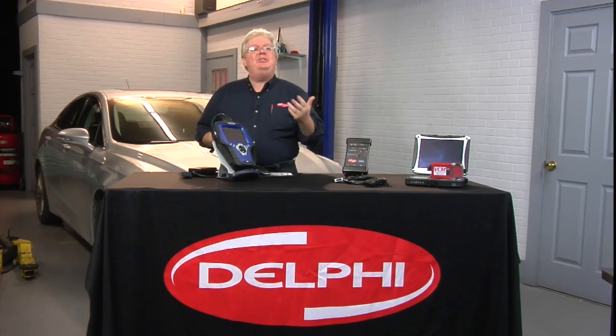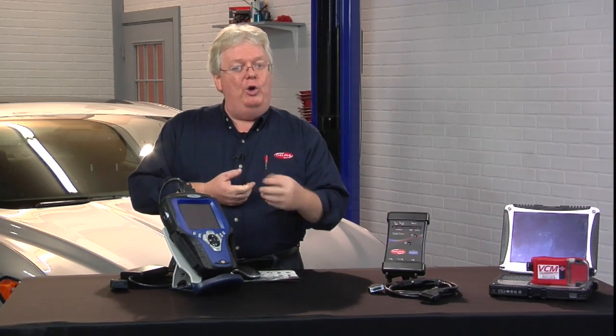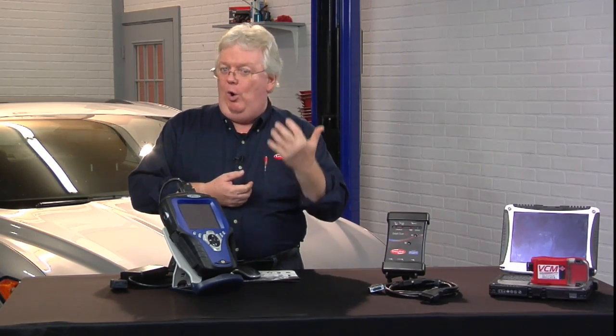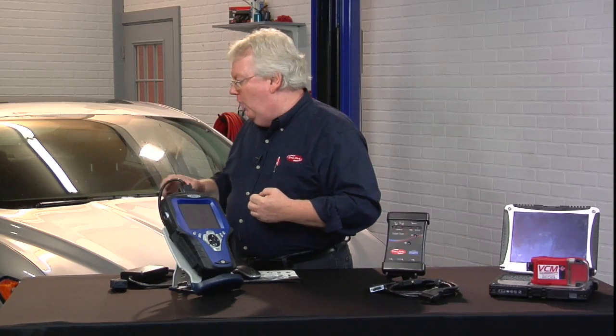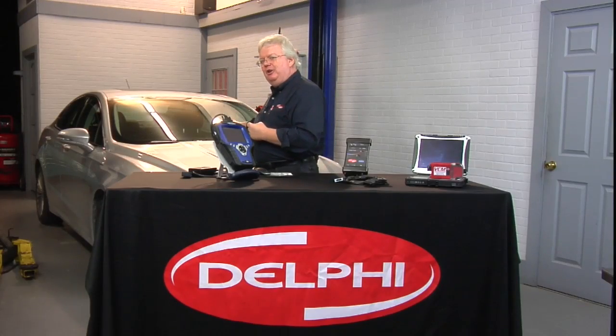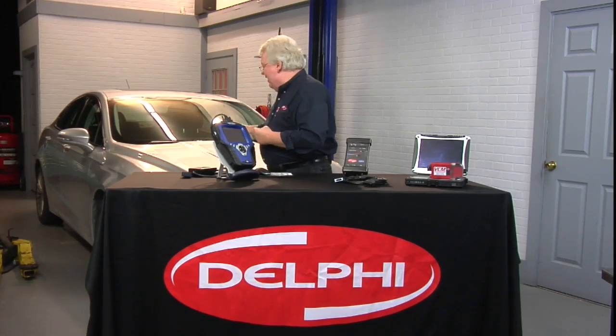Now, comprehensive components, whether it be engine controls or transmission controls, consist of solenoid outputs, sensors, things like that. Those monitors always run. They'll always say complete because we're always checking to see if that mass airflow is putting out a signal or if that throttle position sensor is not below half a volt or, let's say, above 4.5 volts. It's somewhere in that working range. If it falls out of that range, it's an open or a short, we should set a code because the monitor for that runs all the time.